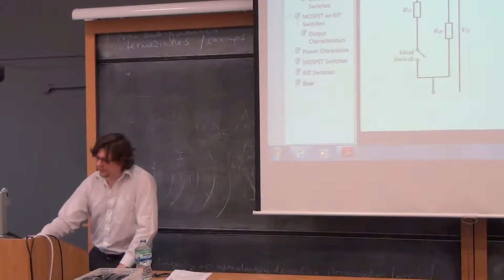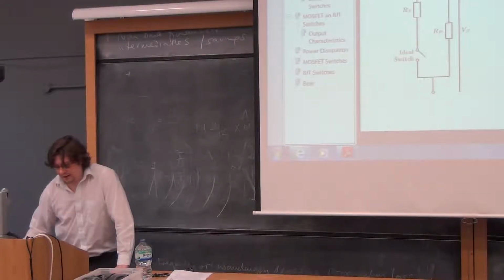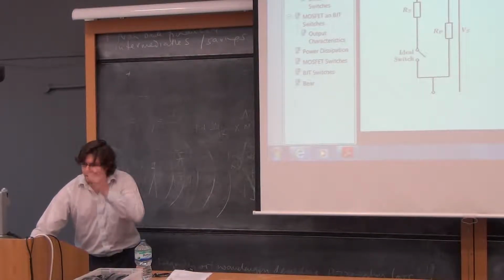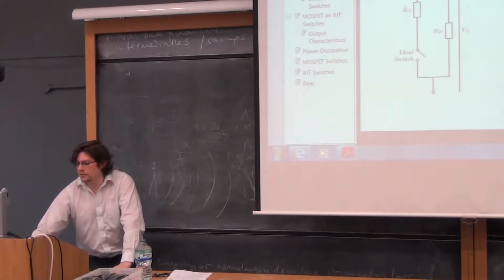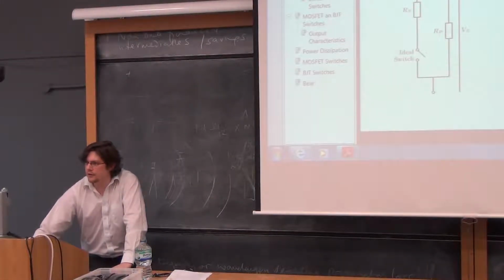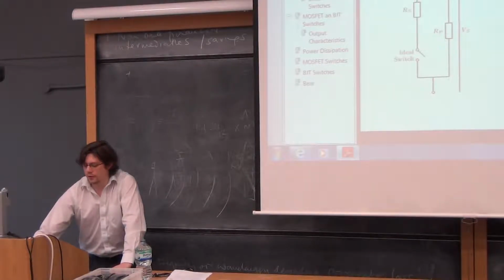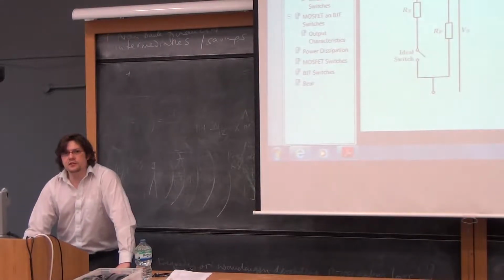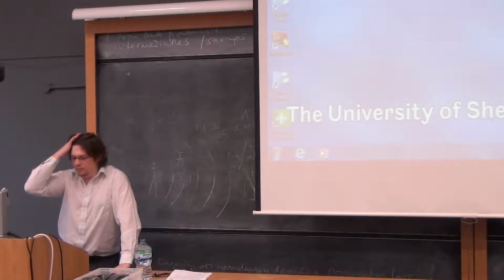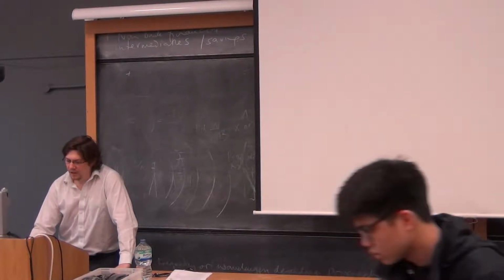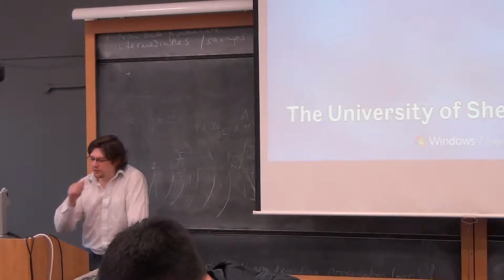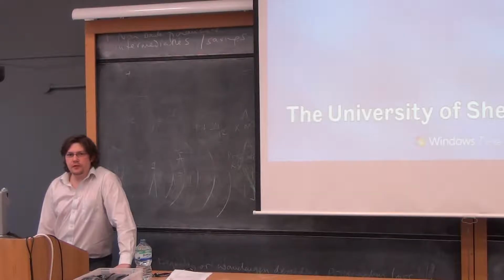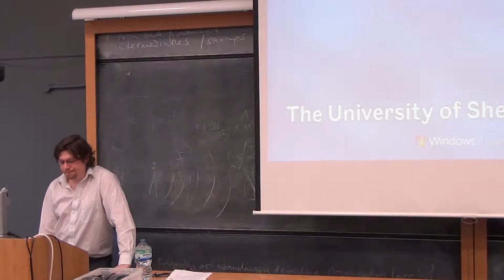Anyway, yesterday we were discussing transistor characteristics, and we looked briefly at numbering systems for devices, that's to say the JEDEC and the Pro Electron system. Then we considered 4 modes of operation for a bipolar transistor, and I drew a kind of graph which showed the 4 modes next to each other in terms of the collector base junction voltage and the base emitter junction voltage. Then we looked at some examples of input, output and transfer characteristics for the bipolar transistor, and I talked for a bit about the sort of graphs that you might find on a data sheet.